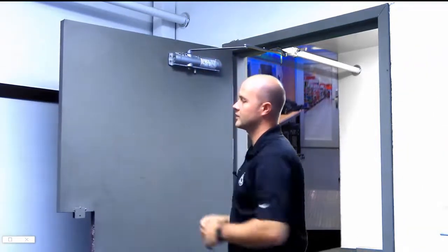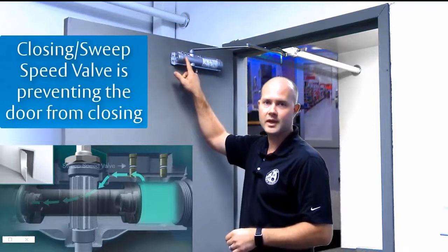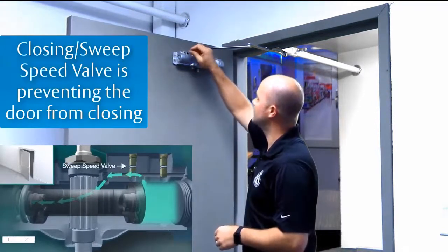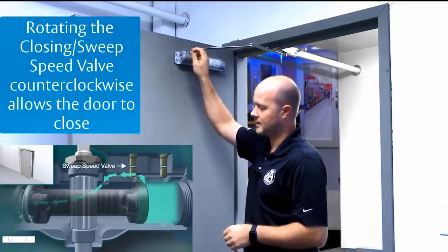Now, if I let go of the door, not touching the door right now, it's not going to close because I'm preventing oil from running through my closing speed valve. I take my Allen wrench and loosen my closing speed valve until I get that timing that I want.